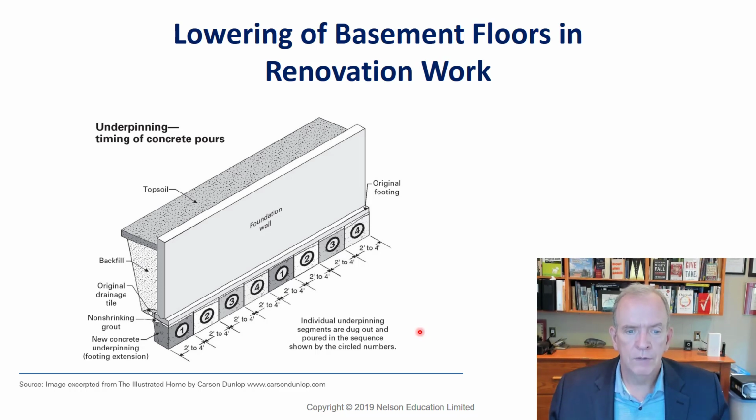You know, the underpinning process could cost easily $50,000 to $100,000, and then you've got all the other issues. You've got the issues of changing the ductwork, changing the staircase, maybe problems with headroom and different things like that you have to deal with in the design, as well as finishing the entire basement. But as I said, you add a lot of square footage. That money could easily be recouped in the new value of the basement. A lot of people may do it too, to add a basement apartment. So you'd have to get the proper permit processes like we talked about. You might have to get zoning changes and other issues rectified to do that.